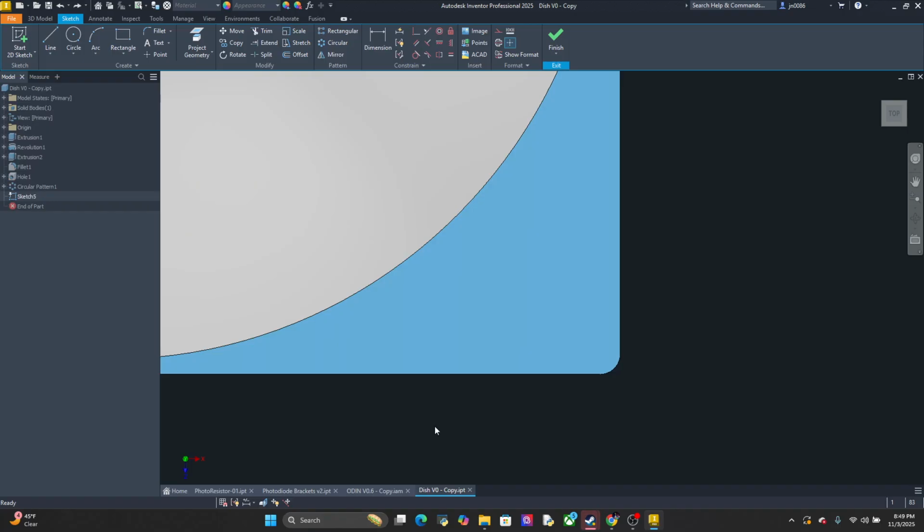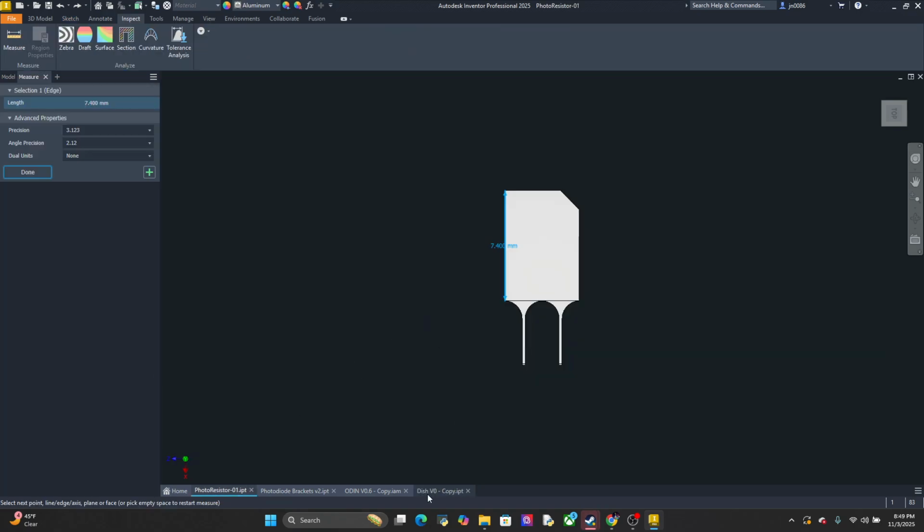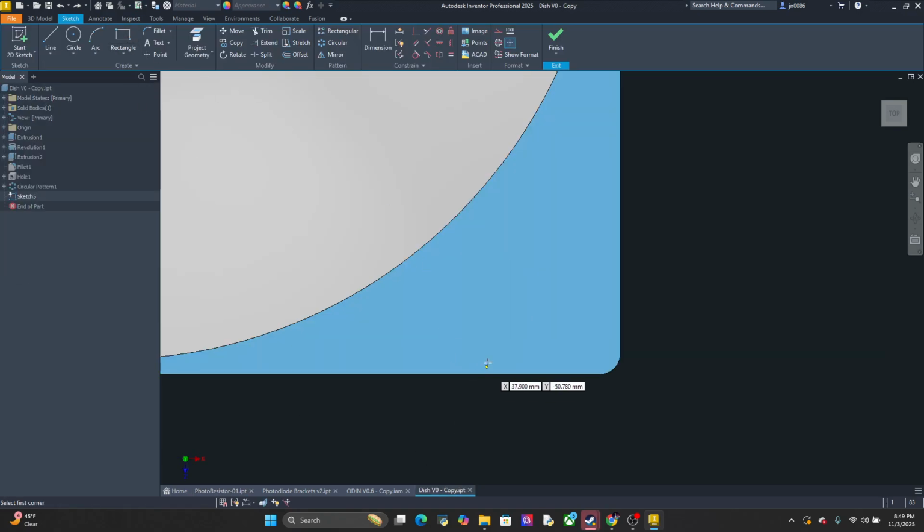So I'll design it like that first, but I'll design a bracket second. I forgot, 7.4. 5.1 is 7.4, so to allow for a little bit of tolerance, we'll have this as like 5.2 and 7.5. Okay, so that fits our little triangle slot.